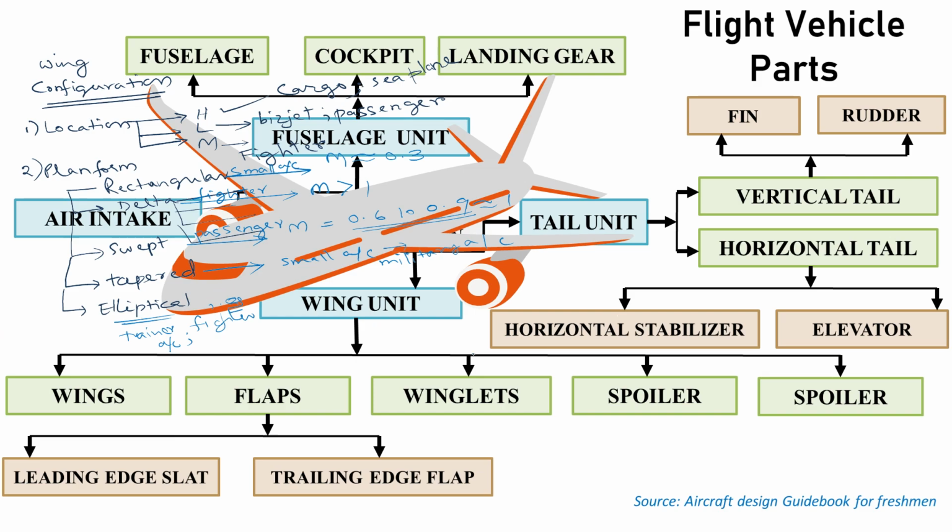Right, now next I will discuss the winglets. Now why do we use winglets in the aircraft? Ma'am, to avoid vortices at the wing tips. Yes, to avoid the tip vortices. So if we use winglets, we can cut down the vortices, so our drag will come down. There are different types of drag. Which drag will come down? Induced drag will come down.